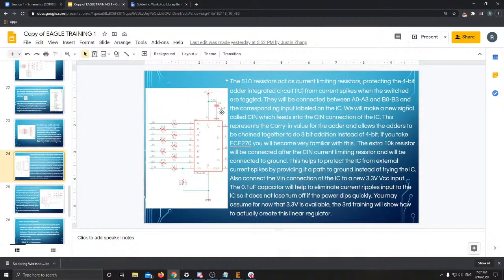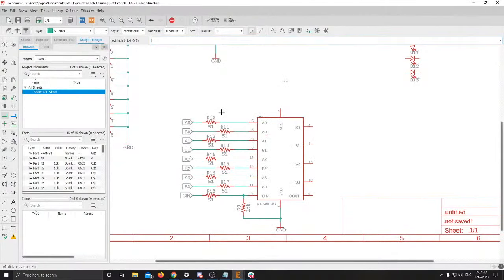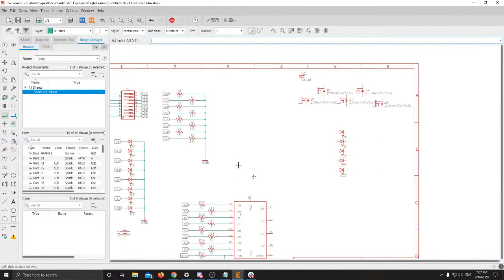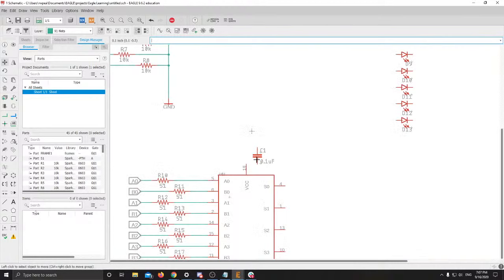So let's say your regulation circuit has a little bit of noise on it and it's switching. This capacitor can help smooth that because it resists that voltage change, so you'll get a little bit less noisy input. A lot of designs will have something like that, and it's usually specified on the specific data sheet for that design. Just something good to know.